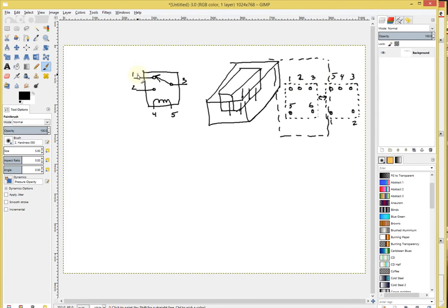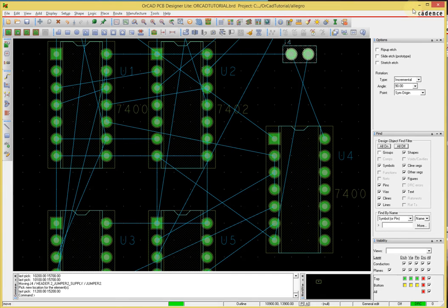So if your symbol pin assignment and the footprint pin assignment do not match the pin assignment that is on the data sheet of your particular component, that's going to be another catastrophic failure, right? And your board is not going to work, even though the component sits nicely on the footprint itself. So that's a very easy way that you can get into a lot of trouble. Just keep that in mind.